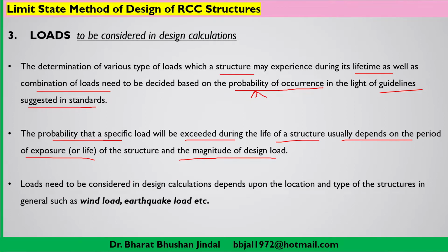Then loads need to be considered in design calculation. They depend upon the location as well as the type of the structure, such as when you are going to consider wind load. When you take the wind load into consideration in the design calculation, that depends on whether the structure is located in such a type of area or zone where wind load is expected to be predominant. Similarly, we can talk about the earthquake load.